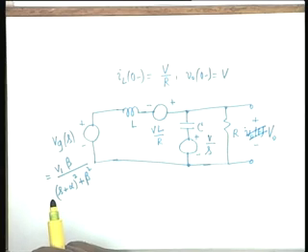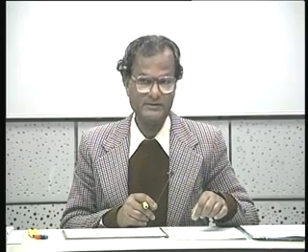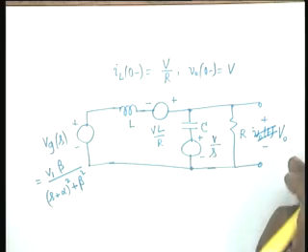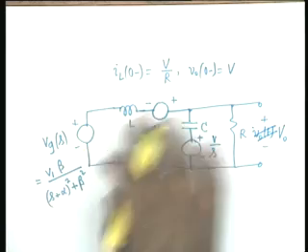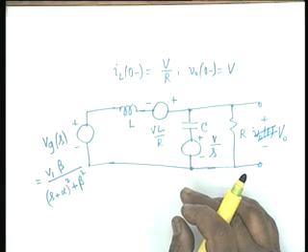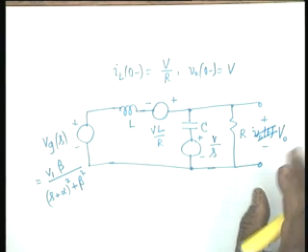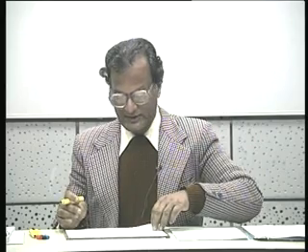The thing that you should notice here is that I am not solving this problem by the transfer function approach. I am not writing the transfer function at all, because there are initial conditions, and if there are initial conditions in the network, the transfer function is not defined. Agreed? You can define a transfer function now, you can define V0 by Vg or any other network, but I could not do it right from the circuit. I could not write in terms of impedances and admittances by inspection, because there are initial conditions. Okay. You can now define a transfer function with those initial conditions.